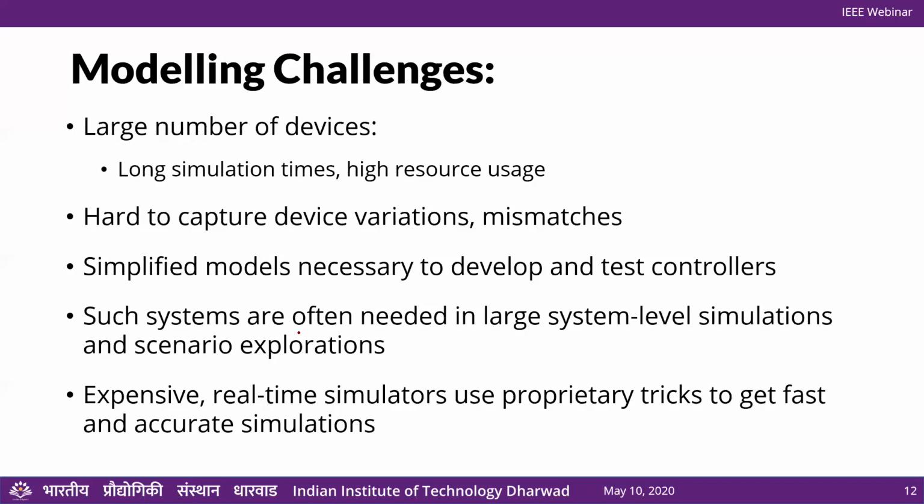And we'll see some of those models in the coming slides. Systems like this, meaning an MMC, are often not simulated by themselves. So it's part of a larger system involving, let's say, transmission lines or some other components, sources, loads, and so on. And so you want a good model that simulates quickly and accurately to be able to do system level simulations, and especially in cases of scenario management.